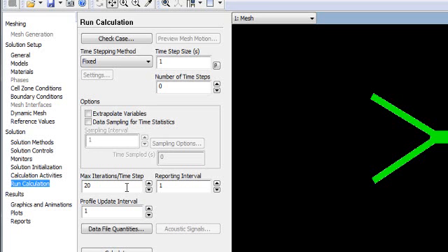When you have a very highly turbulent flow, your time step should be much lower, but when you have a low turbulent flow or laminar flow, your time step will be much higher. So it totally depends on your problem setup. We can also calculate this time step based on the Kolmogorov scale. You can check this online, or in any fluid mechanics book, how to calculate the Kolmogorov scale. Then you will have an idea about the time step.